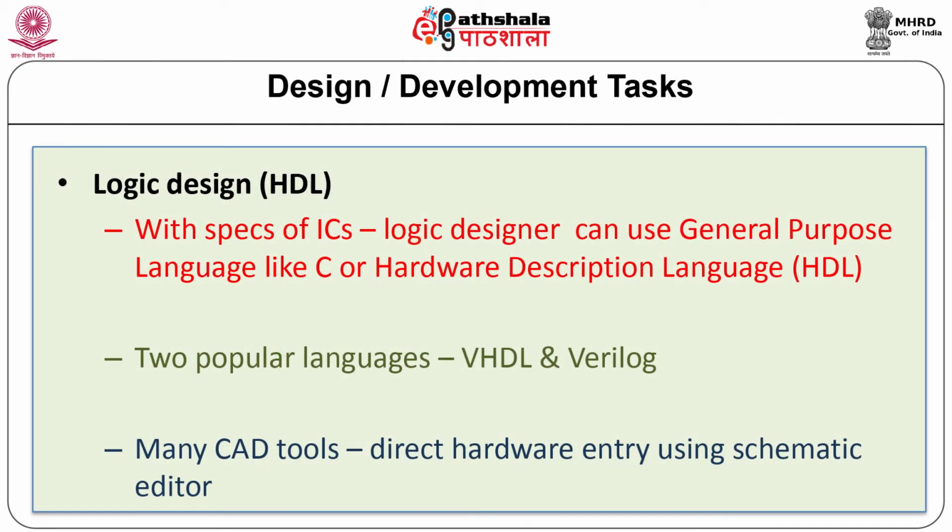Logic design, HDL. As a first step in the design, there is a need to obtain clear specifications of the IC. The designer may begin with initial algorithm to be implemented in the hardware and work purely in the behavioral domain. Some designers use general purpose programming language like C at this level. On the other hand, more and more designers use popular hardware description languages, HDL, to implement the design.